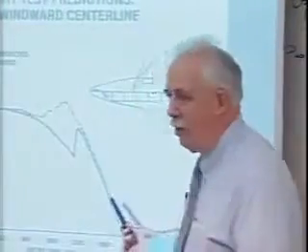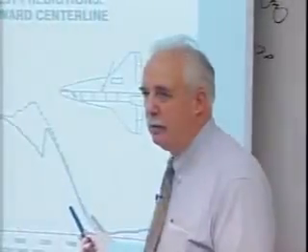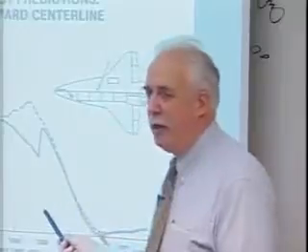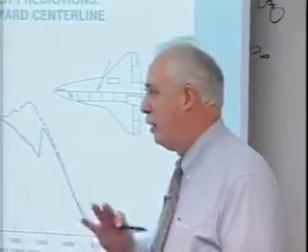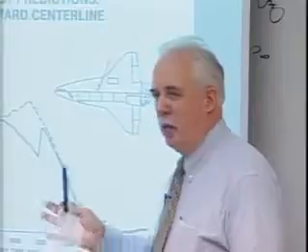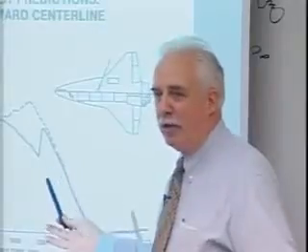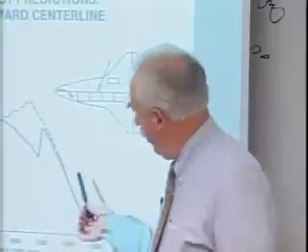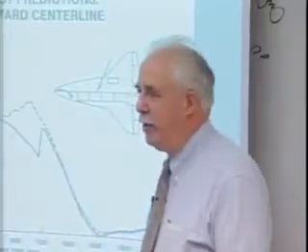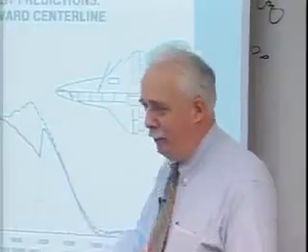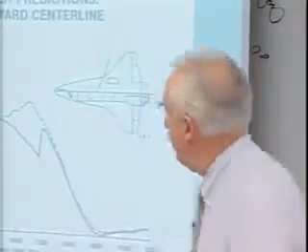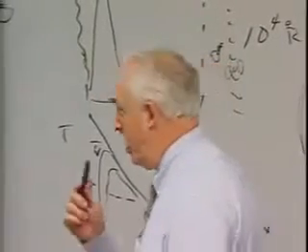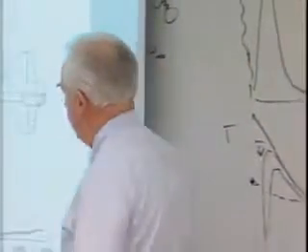the turbulent heating correlated quite well, and that even works with a normal shock Reynolds number. When you go back and look at all of the shuttle data with a crude back of the envelope normal shock, local heating to reference heating, including turbulence, it's amazing. It really is. You know, first order physics seems to hang in there, in spite of all the complications of chemistry and all kinds of things that can happen. You have to be careful, but overall things usually work for it.